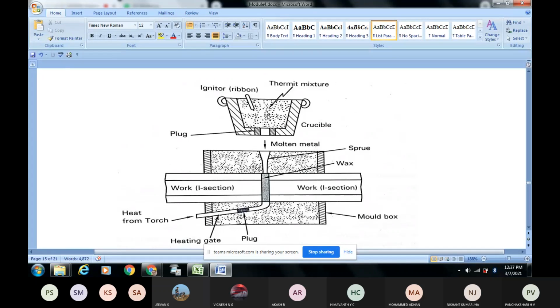See here, that molten liquid is made to flow into the crack area. The molten liquid metal comes flowing down into that crack. Then it is allowed to cool for a sufficiently long period of time. It takes place between part 1 and part 2, so the bonding takes place. After that bonding is over, we remove the molding and everything.